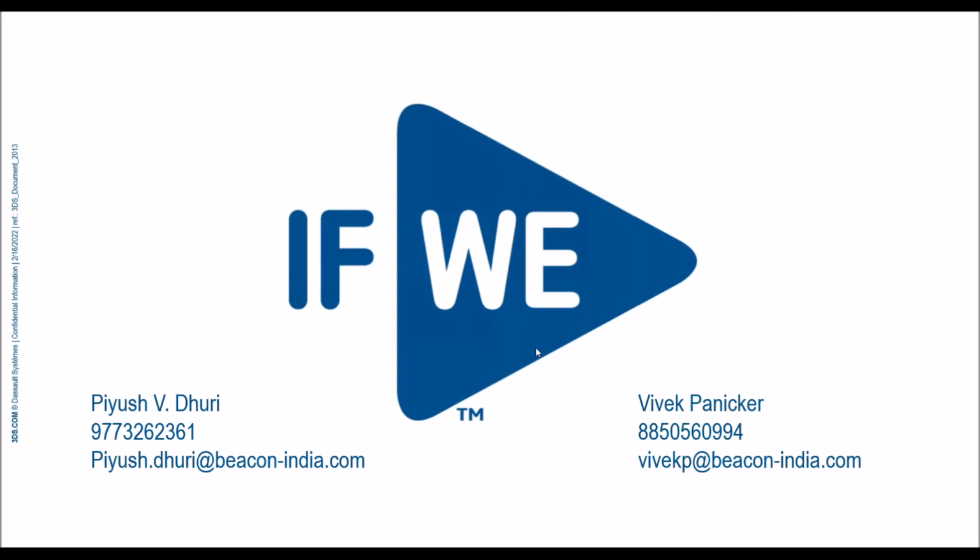Is it more compatible for welded structure analysis? Yes, sir. We have control over what type of properties you want, whether you want to do a solid analysis, a shell membrane analysis, a pure structure analysis or a mixed meshing. So that control we have. If you're talking about a welded structure analysis, we can do a beam analysis where we can define how those node-to-node beams are connected.